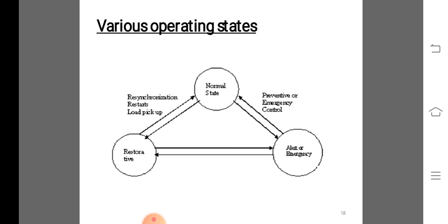All equalities and inequalities are satisfied, but in the event of a disturbance, the system may not have all the inequality constraints satisfied. If a severe disturbance occurs, the system will be pushed into the emergency state. To bring the system back to a secure state, preventive control action is carried out.